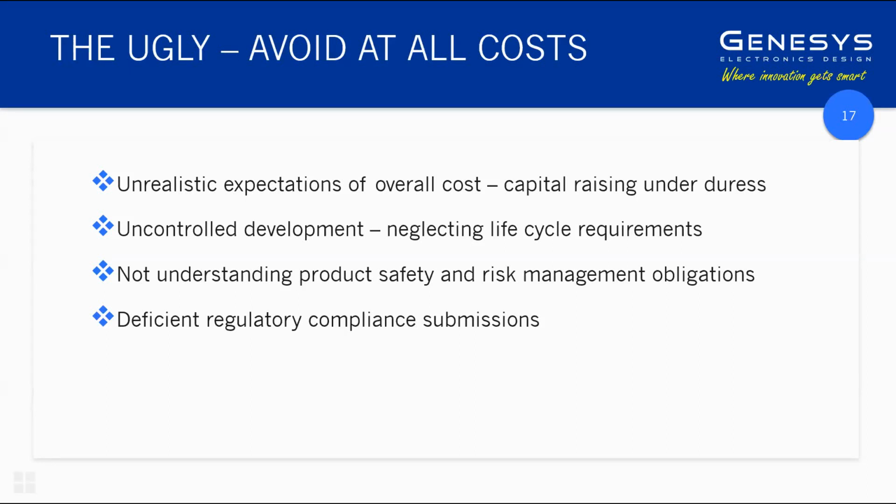The medical quality requirements have built in a concept called product life cycle, and it's very explicit for the software and not so explicit for the hardware, but it is implied. This means that to end up with a compliant design, you have to start with planning at day one. You can't take the concept of "I'll just develop this willy-nilly and then partway through get the compliance people to do all that stuff for me." It simply doesn't work when you look at the fact that you have to start with planning and specification right at the get-go, under the control of what's called the life cycle model.